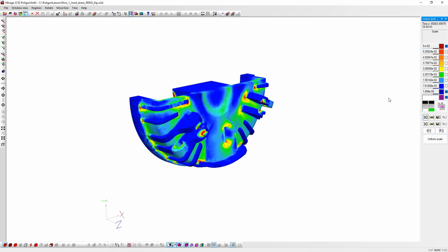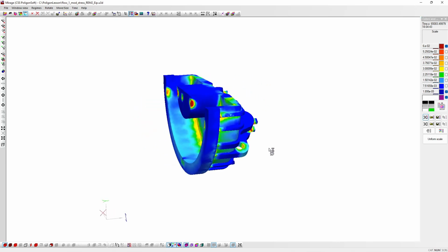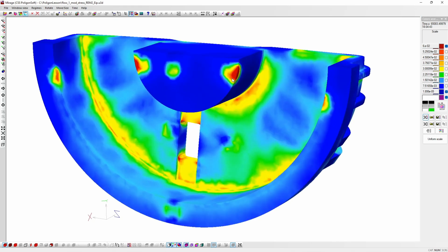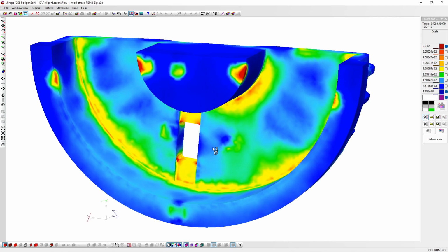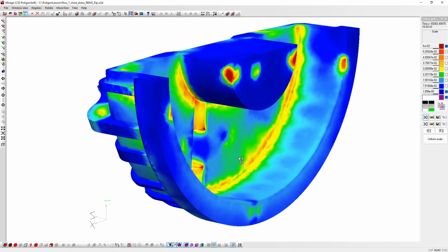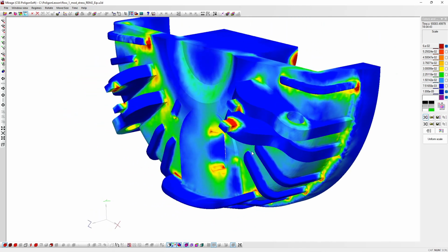Here we see the following picture. These are the places where the plastic strains are greatest in this casting block. It is precisely by the plastic strains that we can assume that where they are maximum, there will be the highest probability of fracture. As we can see, the risk areas are the places where the feeders were previously attached. I would recommend completely changing the scheme of their connection.